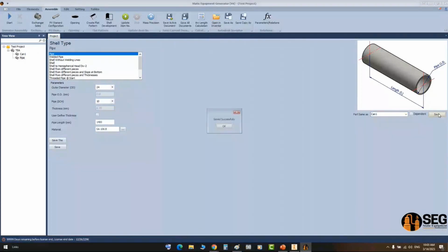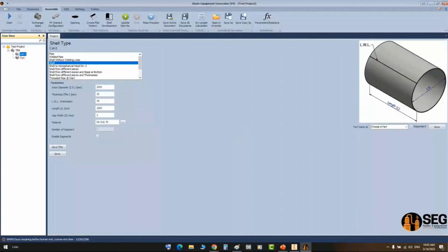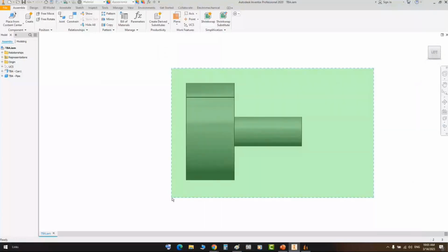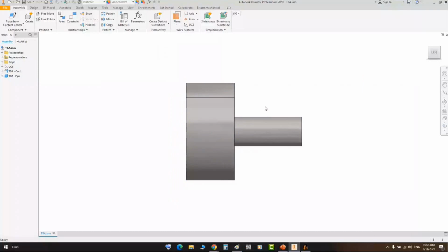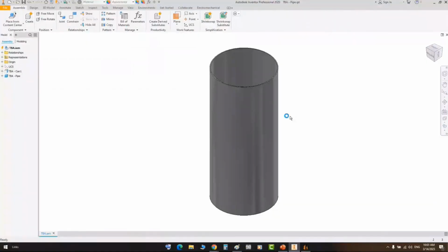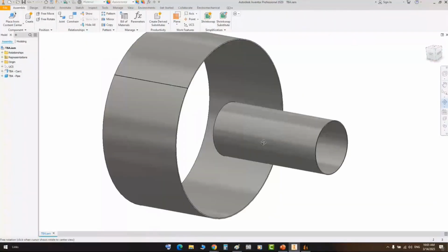When you click on save, now if you move to another point and come back to this pipe, you will find the information of this node changed from pipe to a shell. Now this mistake may take place when you generate the 3D model. In case you still have not generated the 3D model, nothing will take place. But after creating the 3D model, when you click on Start Assembly, you will get an issue during the creating of this part. You will not find it updated.